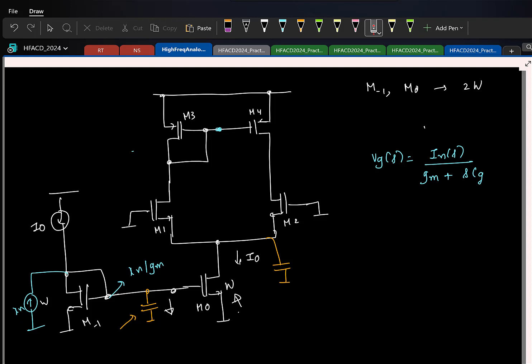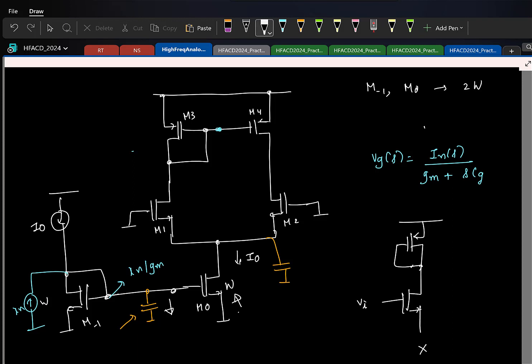Remember that earlier, let's say this guy was open for small signals. If I draw the common mode half circuit, for common mode both these guys are the same. I'll short it. You'll have a diode connected device here. This will be open. Now if I apply any common mode signal here, there is no path for the incremental current to flow. Common mode response is 0.